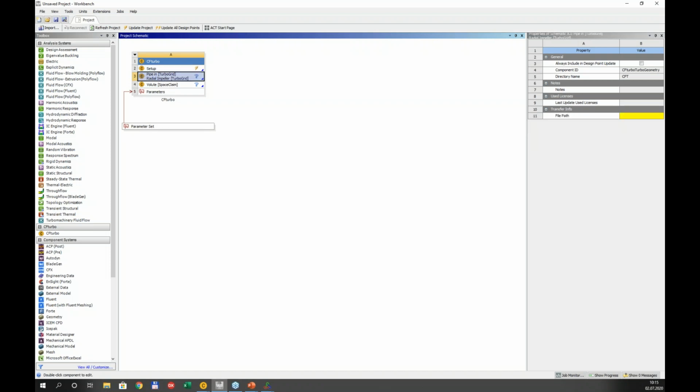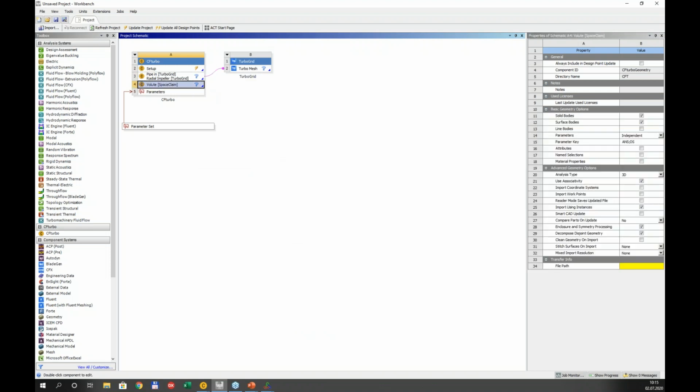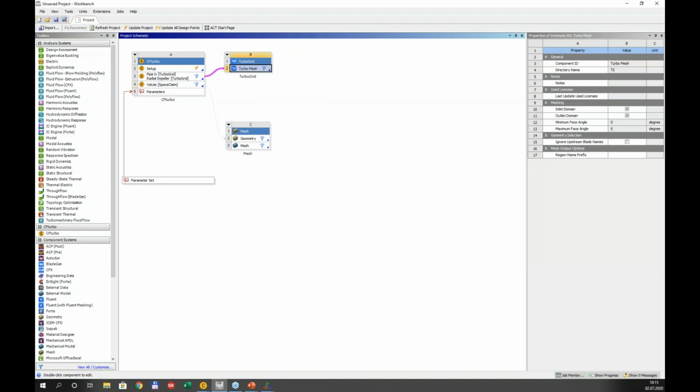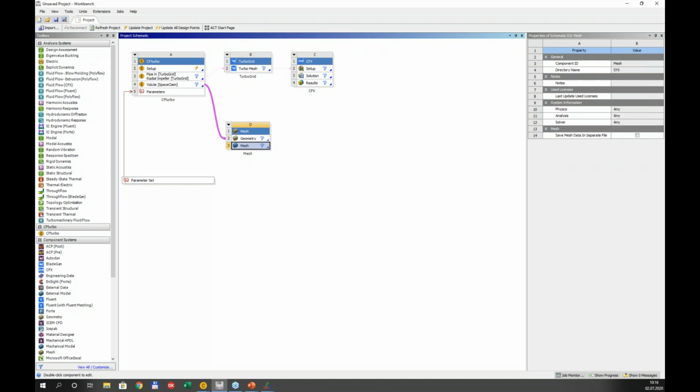Okay, I'm not going through all the steps to set up the workflow, but quickly I want to show you how to make the most important ones. The impeller and the inlet stator should be meshed with the help of TurboGrid. This is added here, whereas the volute should be meshed with the Ansys Mesher. And once this is done, of course, that has to be guided through the simulation node, which is CFX in this case. And the same, of course, applies to the volute.